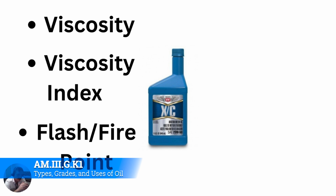Now, all this engine oil is set to withstand normal operating temperatures of engines. But this is also why high engine oil temperature becomes a serious concern, for a couple of reasons. One, it starts to lose its ability to cool the engine. Number two, you start approaching its flash and fire points, so it can catch on fire. And number three, as it off-gases, the closer it gets there, it builds up more and more pressure, and the engine can only take so much pressure. Just like anything, if you have a water bottle and you keep filling it up with air, eventually it'll pop. Engines are no different; they just have a lot more strength. So that's something to keep in mind with engine oil.